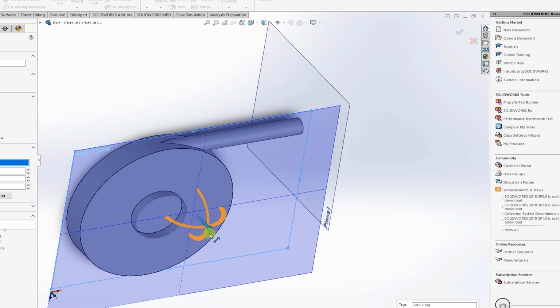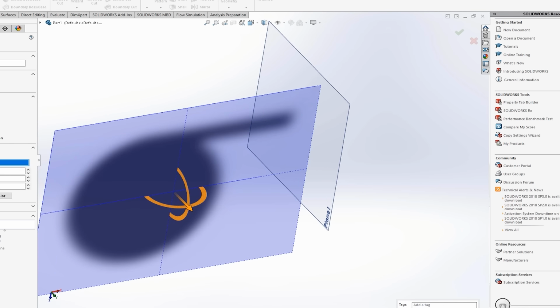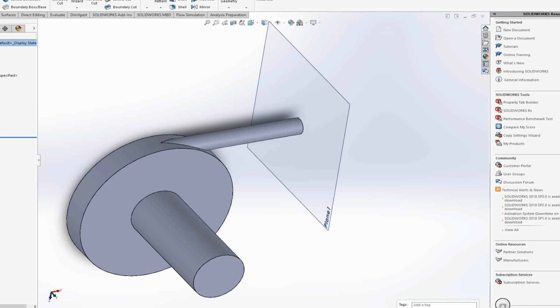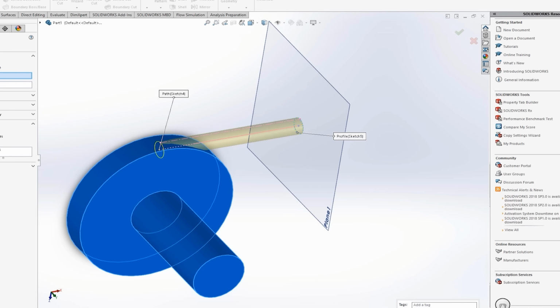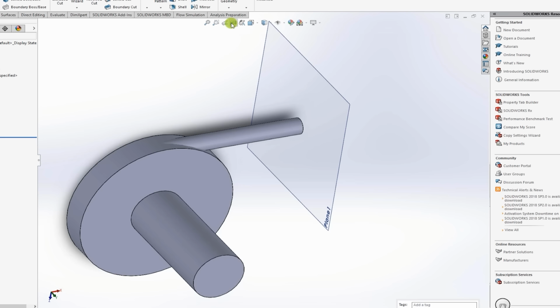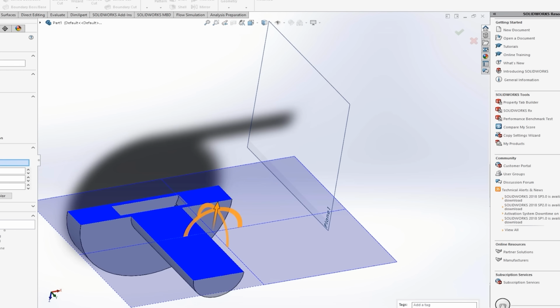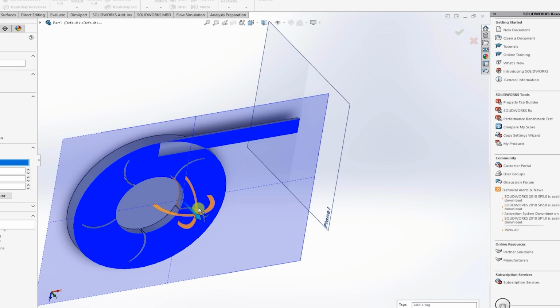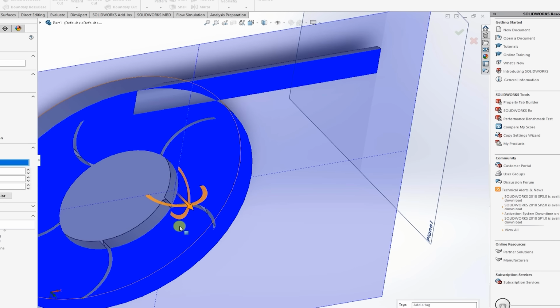Now you can see that the volute has been merged, but the problem is our impeller is missing. Why is that? If you go back to the sweep tool, there is an option called Options. Expand that, and you will see that merge results has been selected. This needs to be unchecked. If you hit OK and go back to our section view, modify planes, there we go. You can see that our impeller is there, nice and clean.